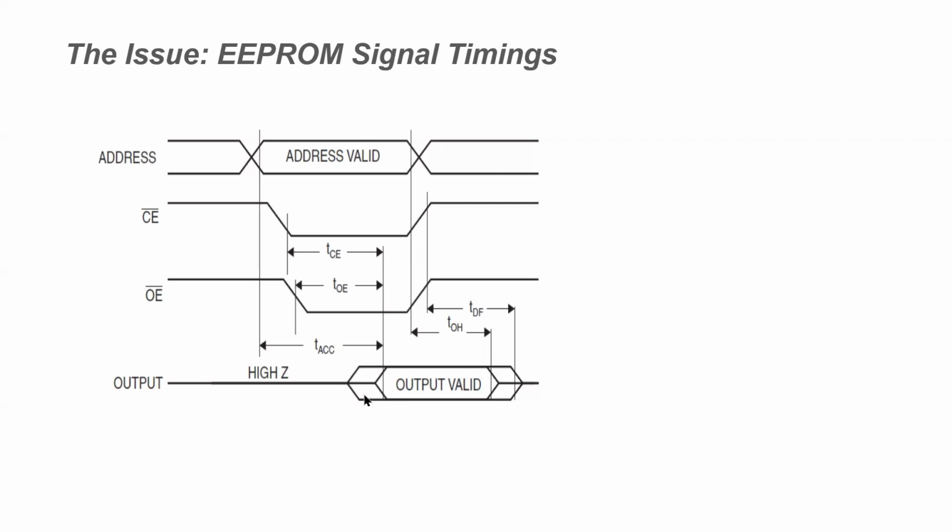And if these bits are connected to our control lines that, let's say, provide the tick counter reset, that's a really big problem, because if the tick counter reset signal goes high, that's effectively shortcutting the currently executing instruction and beginning the next instruction.